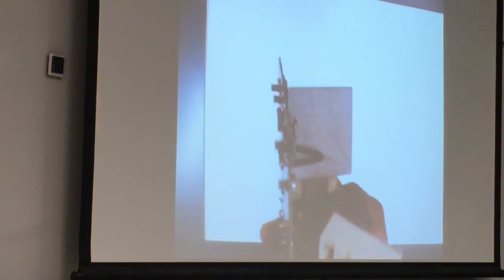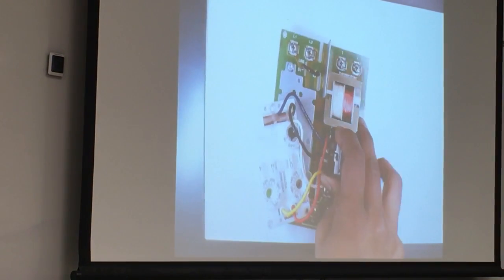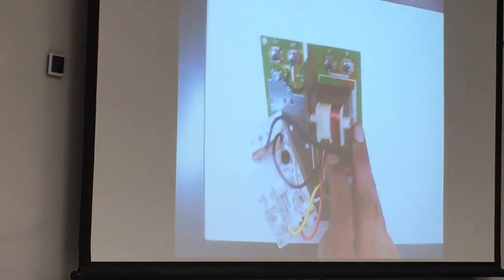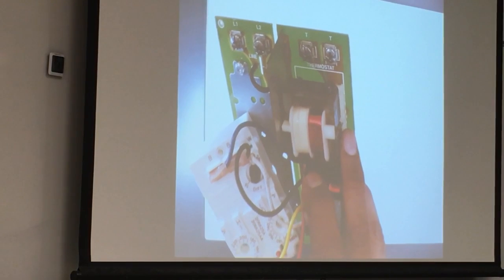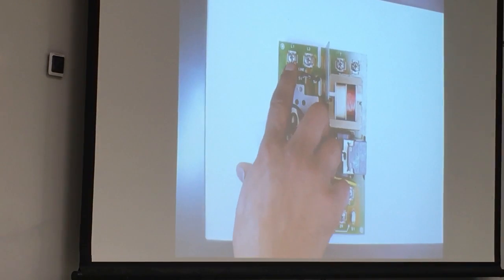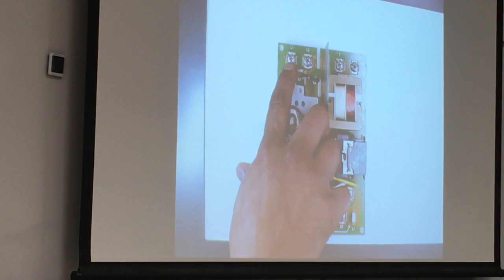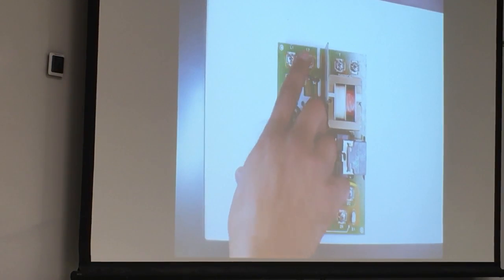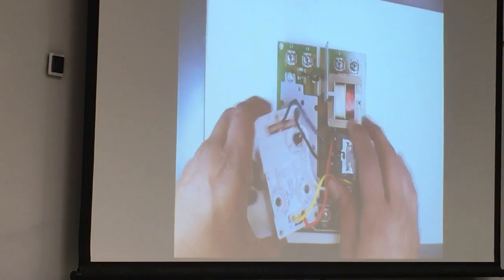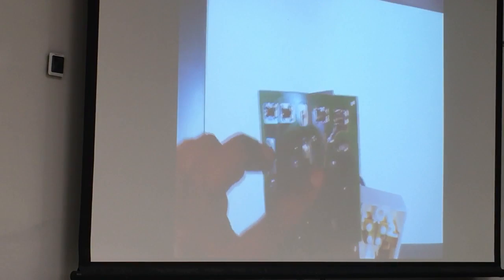But this company is very generous in putting things on the board. Sometimes it's not going to say thermostat, because they also have limited space. Some boards are very crowded, they cannot print stuff on them. What do you think L1 is? Line one. Hot. Excellent, it's hot. Line 2? Neutral. Fantastic.